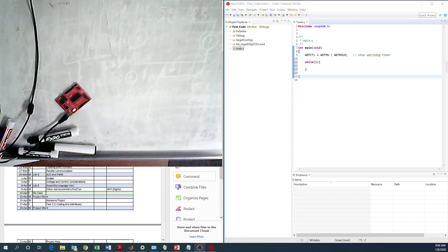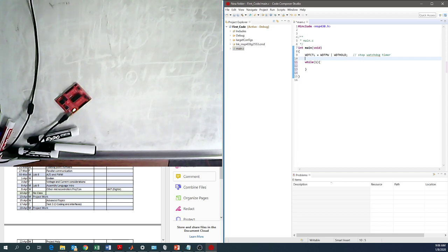The GPIO pins can be an input or an output. And so the first thing that I'm going to do here is I'm going to take this predefined thing, P1 dir. I'm going to make it equal to, we'll change this in the future, but 0x01. That's a hex value. I also could have said 1, make pin 1.0 an output. And so this is a little confusing because we have to realize that that's in hexadecimal in P1 dir. We have to talk about hex just a little bit. But let's go for it.